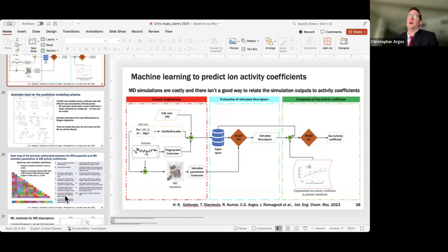The other question, on membrane conditioning: in our phosphate removal work, we knew from a different project that it was very hard to get phosphate through the AEM at first. If you just stuck the AEM in the chloride form in the cell and fed it a phosphate solution like sodium phosphate, we got very little phosphate removal.